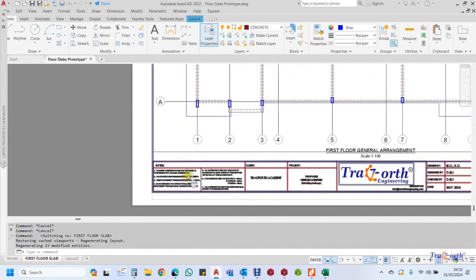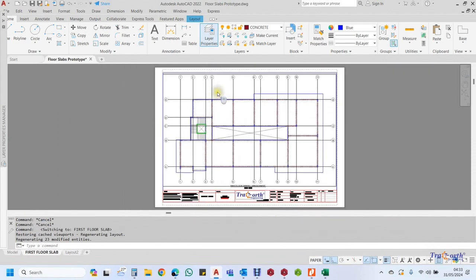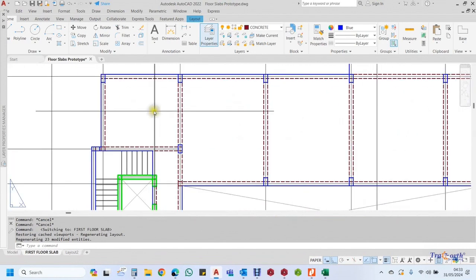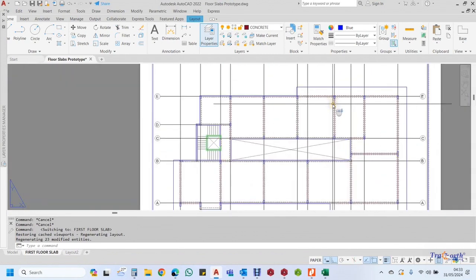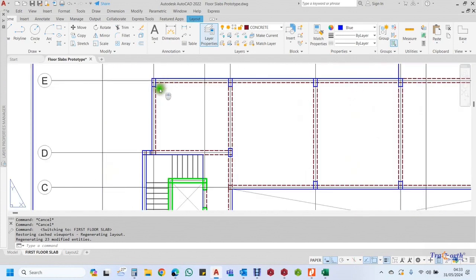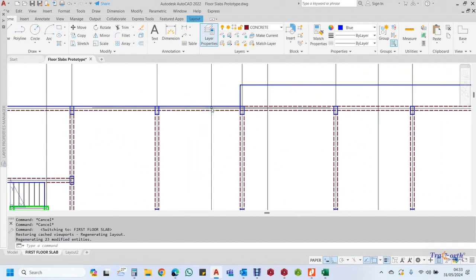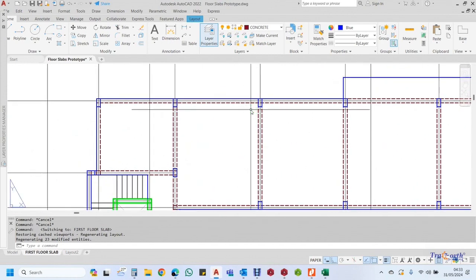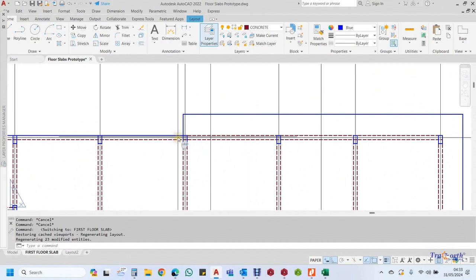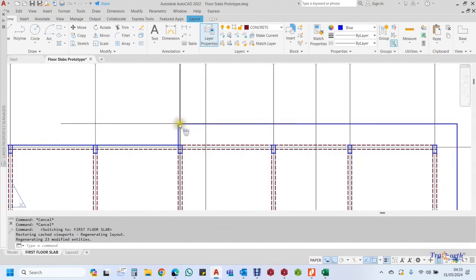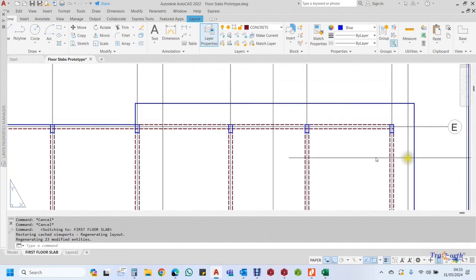Now, if we have a slab, first, from elementary drawing, when you have a dotted line, that means the line is hidden. So in this case, what we have here is an edge of our slab because it's continuous. Wherever it's continuous, you know you are seeing the edge of the slab. So in this case, because it's a single line here, that means it is a cantilever.